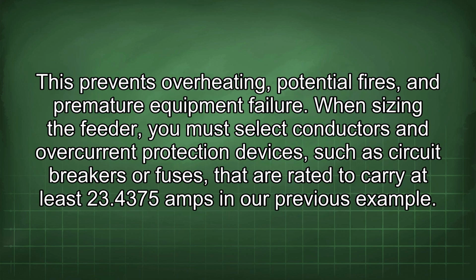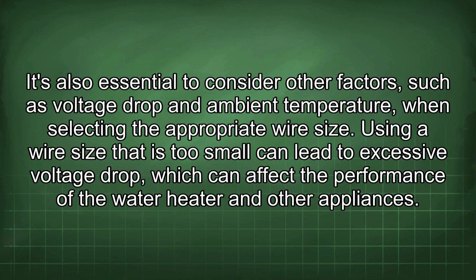This prevents overheating, potential fires, and premature equipment failure. When sizing the feeder, you must select conductors and overcurrent protection devices, such as circuit breakers or fuses, that are rated to carry at least 23.4375 amps in our previous example. It's also essential to consider other factors such as voltage drop and ambient temperature when selecting the appropriate wire size.